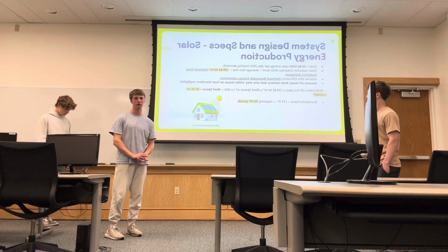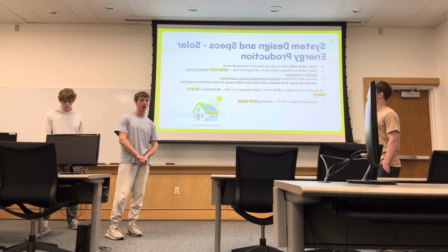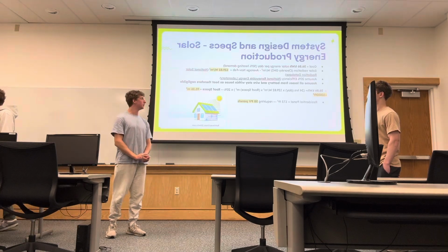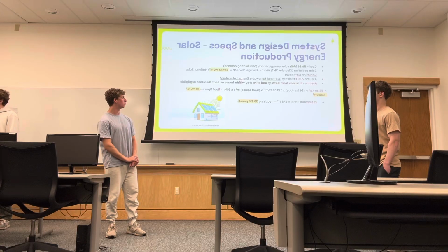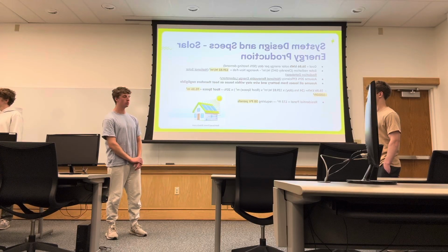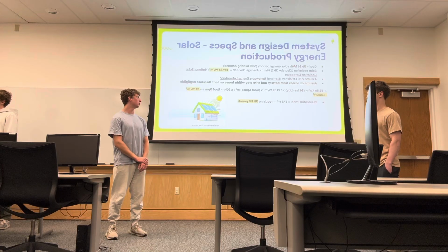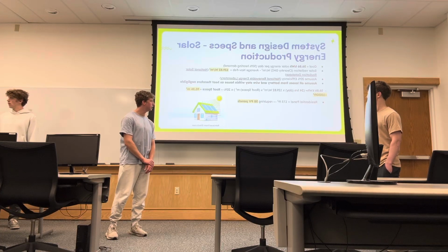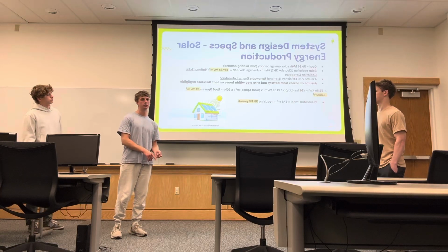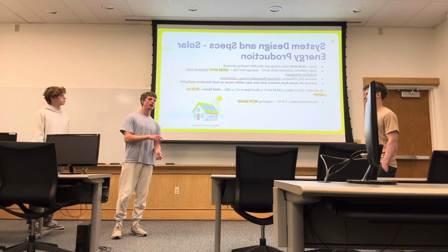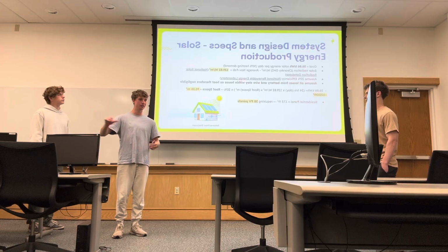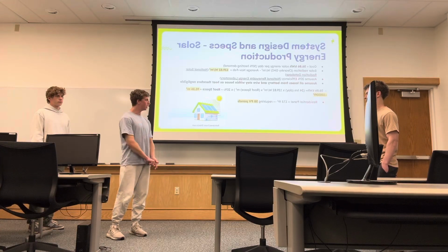So using solar radiation found from the National Solar Radiation Database, we found the clear sky GHI, which is used to determine the watts per meter squared from solar radiation. We found the average day and night to be just under 130 watts per meter squared. So assuming a 20% efficiency, which is standard according to the National Renewable Energy Laboratory, and assuming there were no other losses from the wiring, since they're so small it'd be negligible, and a battery, we assumed any losses from the battery would just be converted into heat into the house, which is where we want the heat.